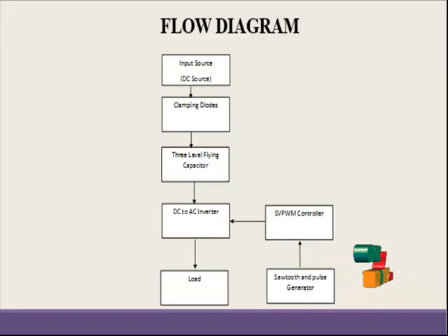In this topology, the principle of the 3-level topology can be extended for use in topologies with any number of levels. In practical experience, the topology is technically difficult and complicated for high power converters. The first practical multi-level topology is the neutral point clamped PWM topology. The 3-level versions of the topology have several advantages over 2-level topologies. The drawback of flying capacitor multi-level inverters is